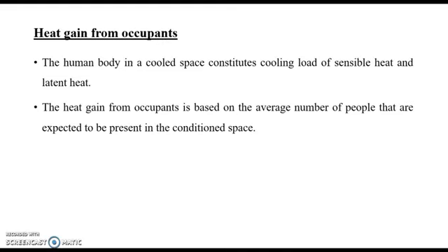So we account for the amount of heat released from each occupant. The human body in a cooled space constitutes a cooling load of sensible heat and latent heat. The heat gained from occupants is based on the average number of people expected to be present in the conditioned space.